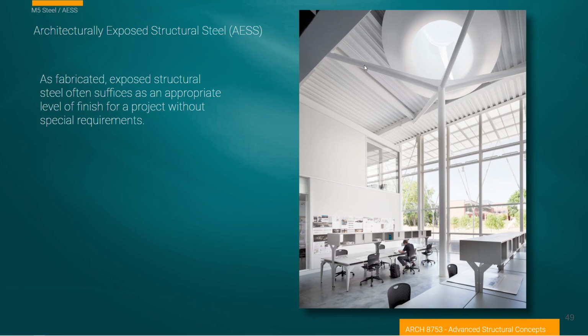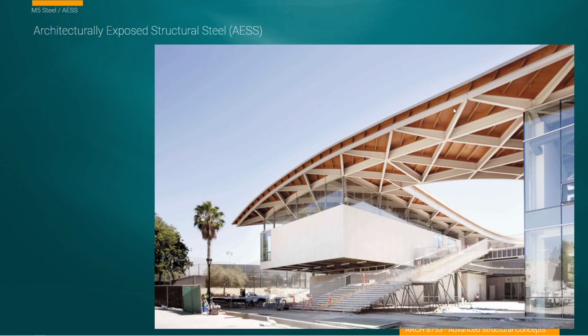But you can see this, one of the nice things about this is these are actually tapering, and you can see where the maximum moment or loads on these members, because they're working as lever arms, is where they make attachment to the column. So they actually thicken up at that point. So here we have some more, I think, really beautiful examples of exposed structural steel.